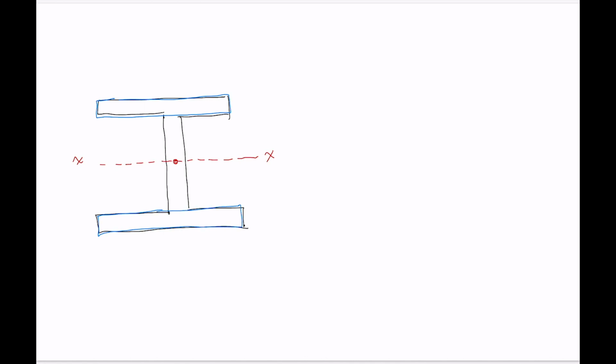If my drawing was great. Let's call those shape number 1 and the center piece shape number 2 here. What would be tempting to do would be to say that Ixx for the whole cross section is equal to 2 times I1 plus I2. But this is not correct.